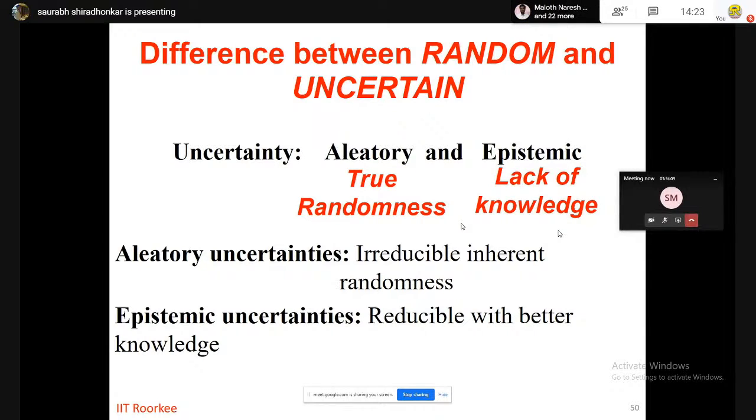Okay. So as I was saying, the uncertainties associated with seismic hazard, you could say they are aleatory uncertainties, while the uncertainties associated with the structural response, you could say they are epistemic uncertainties. This is a broad classification. Again, aleatory uncertainties cannot be reduced because we will never know the exact fault line and the possibility of earthquakes. While the epistemic uncertainties, like the structural capacity, we can know because we can do structural testing of various building configurations in the laboratories, and that's how we can reduce the epistemic uncertainties.